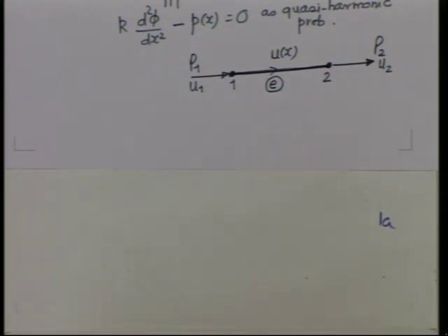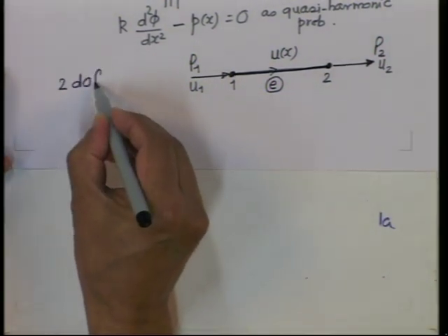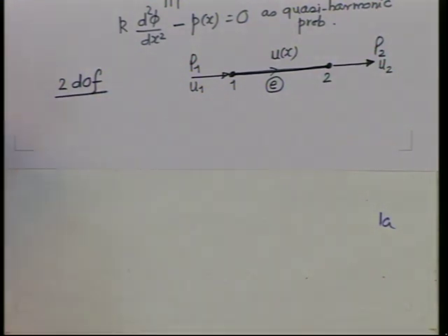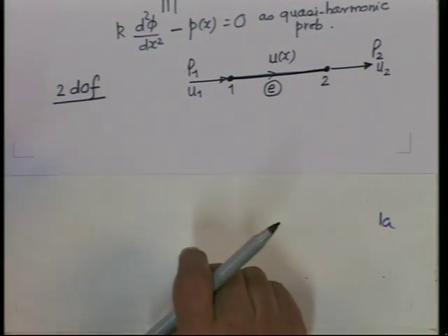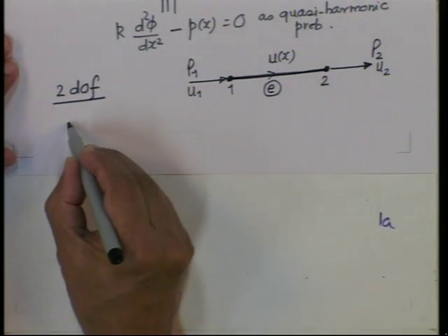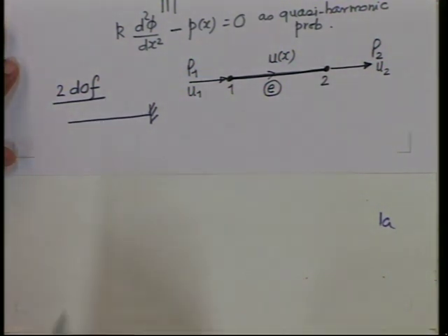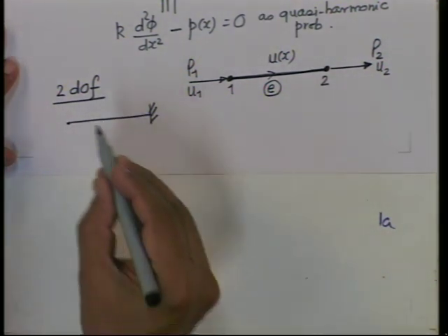For example, we learn from structural analysis that this is very simple, it has got 2 degrees of freedom. So, I can relate these two forces to two displacements by setting one displacement 0 at a time. So, I have a simple problem in which I fix 2 and only apply at 1.